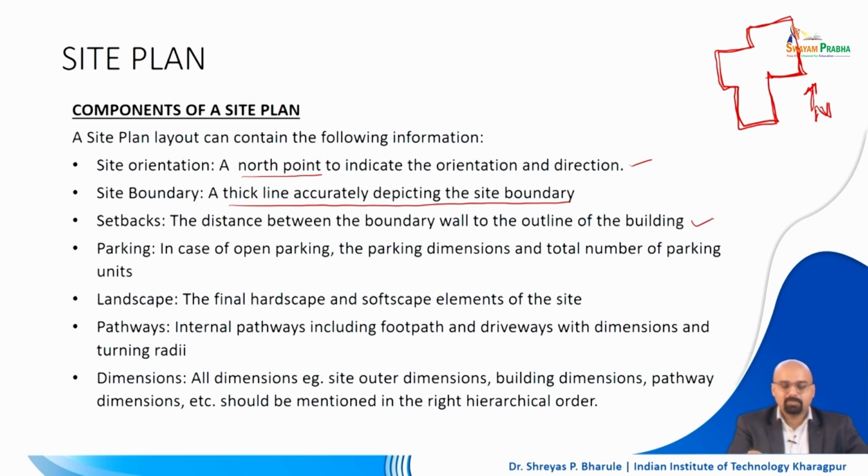Next, you need to demarcate the setbacks, right. So, the distance between the site line, where the site is, and say for example, you are going to have a house which is like this, right, and there probably is another pool or something like that here. So, in this block you need to demarcate where the setback is, how much the setback is from the individual site boundaries which are there, right. All of these distances are to be measured and shown. So, that becomes really important.